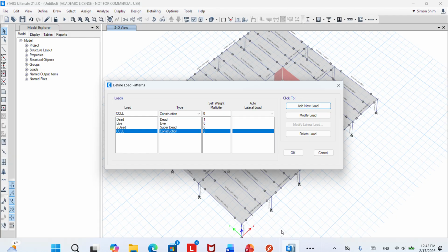So composite beam design is actually twofold. During the construction, you could think of it: you erect the column, you erect the girder, you erect the steel beam. Now you put the metal deck, right? You weld the studs, wire mesh, you pour the concrete. At that time, concrete doesn't have any strength. It's weight alone, wet concrete, right? It doesn't contribute any stiffness or strength. So that is the construction phase. That means only the bare steel should support those loads, right?